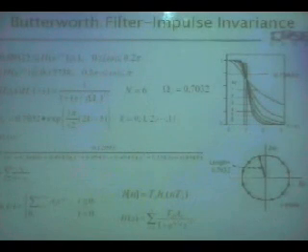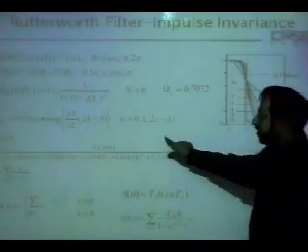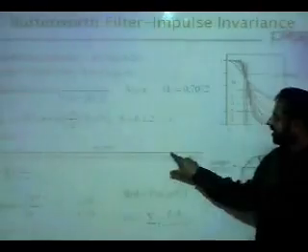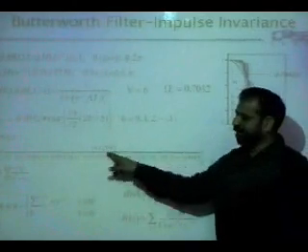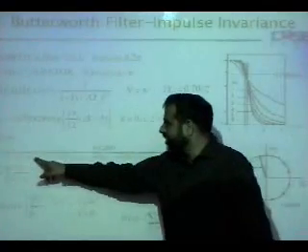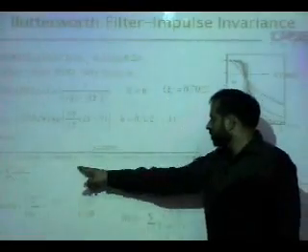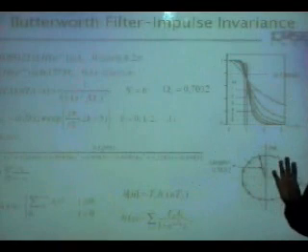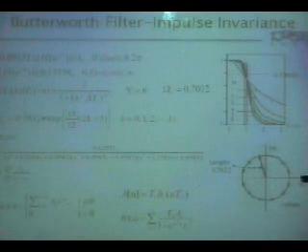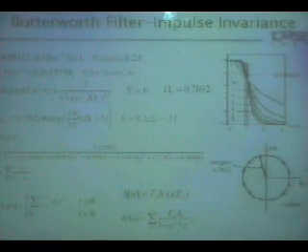End of the day, it will give you a transfer function which looks like this. H of S is equal to 0.12093 divided by S squared plus S plus this, so 3 S-squared terms, meaning 2, 2, 2, 6. It's 6 poles, 1, 2, 3, 4, 5, 6.